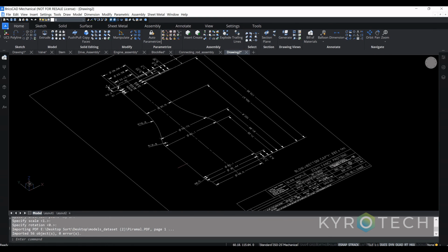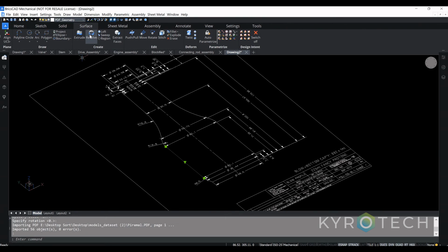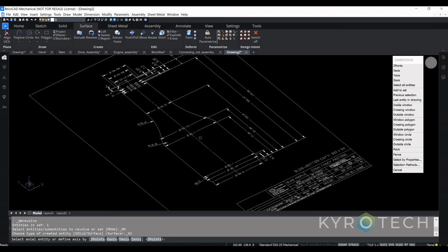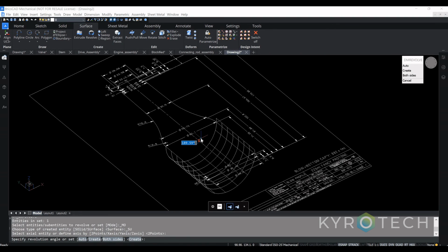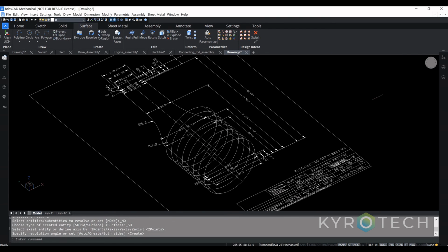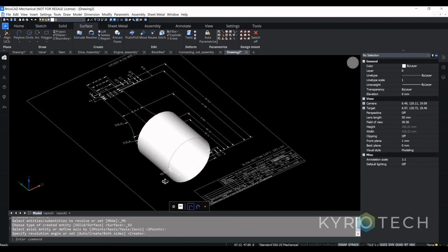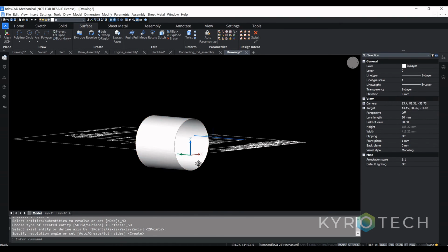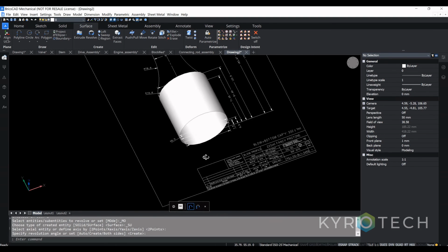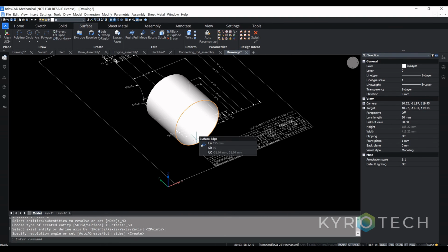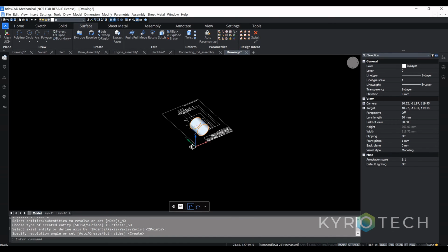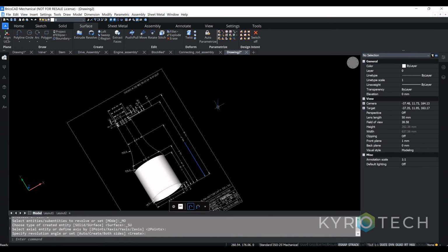Now if you can just see, this is a line. You can edit it. You can also convert it into 3D. Suppose you want to go to surface modeling and you want to revolve, and let's say I want this axis and I want to do 360 degrees, and just shift to the modeling option. Okay, now you can just see over here, I just converted my PDF file into 3D directly within a couple of minutes. This is how BricsCAD gives you this option.